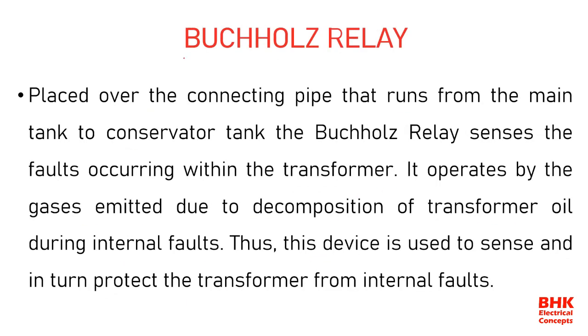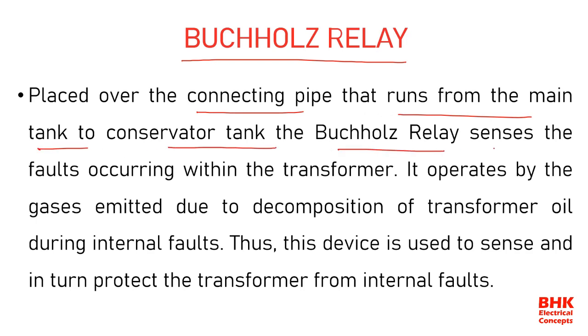And coming to another most important thing, that is the Buchholz relay. So here, it is placed over the connecting pipe that runs from the main tank to the conservator tank. The Buchholz relay senses the faults occurring within the transformer. Okay, so here the Buchholz relay senses the faults occurring within the transformer.